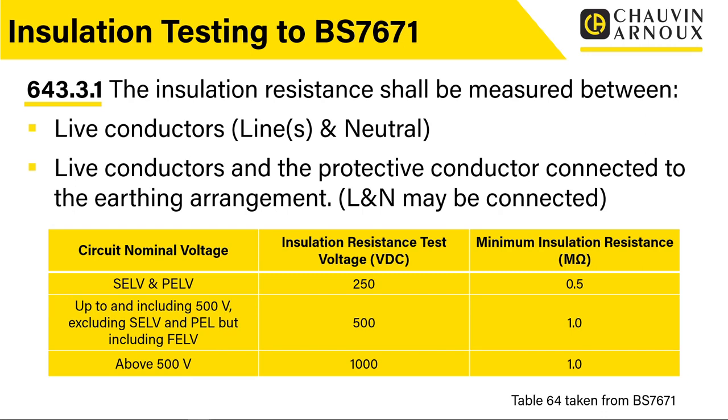Therefore, if we had a fault between our live conductors and something connected to earth, we would pick that up during this test. Whereas if we were just checking to the cable with it floating, all we are checking is that floating conductor. So we're not actually checking to the general mass of earth and the earthing within the installation, the equipotential bonding and all that sort of thing.